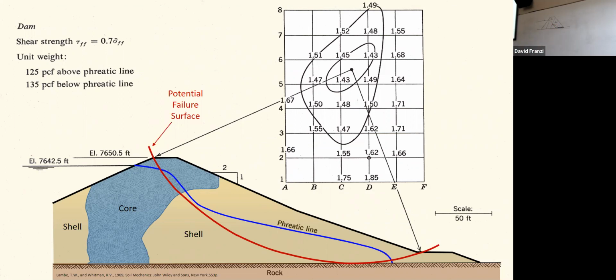Yes. Would that just destroy the shell on the core by taking particles out of it, though? You mean that they would wash into here? Yes. Not if you design it right. There are very specific requirements for drainage. So you don't just take a bunch of rocks and throw it in the trench and call that a drain. Basically, you design it with finer permeable material, and you get progressively coarser. And then you get progressively finer again. And the idea is that those fine layers prevent particles from washing into the really coarse stuff that's in the interior of that drain.